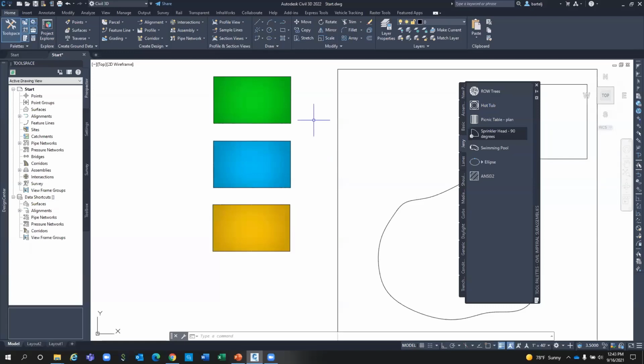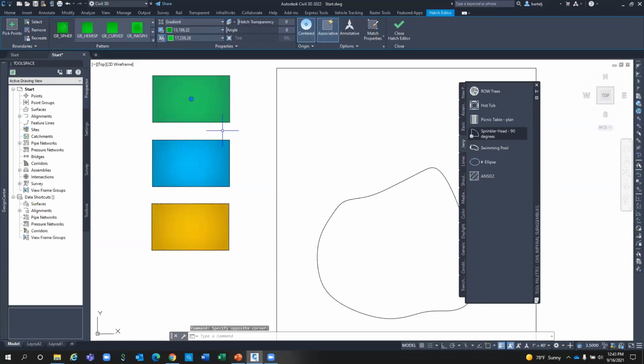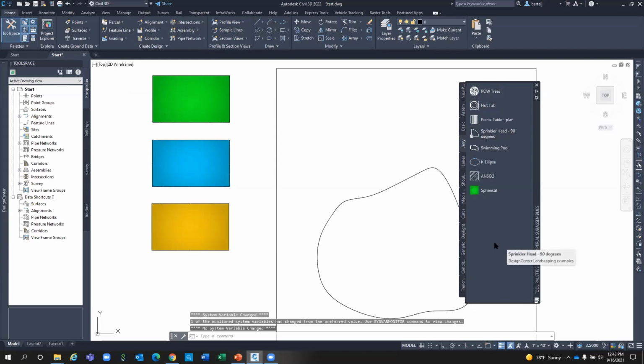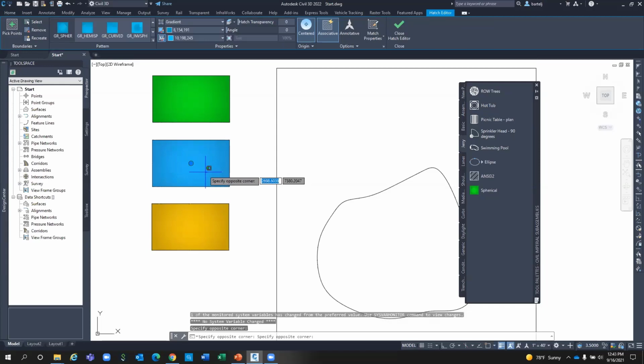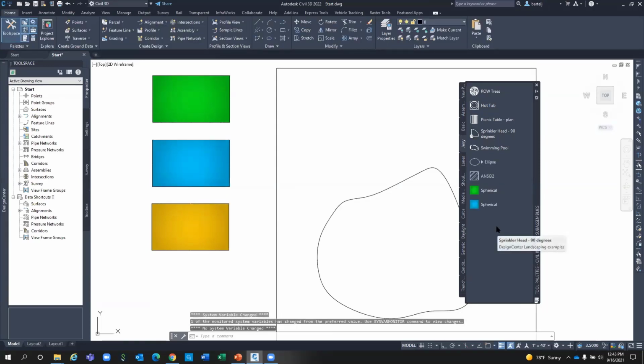I want to bring this up because I used to do this kind of like a paint by numbers type deal. But if you create gradient hatches and you're going to drag one of those onto the tool palette, the interesting thing is rather than pick and then left pick and hold, we have to pick again, and then left pick and hold, and then drag it on there. All right, why do we have to do that? That's a great question. I wish I had a great answer for you, but I don't. Just know that if I'm going to do things with gradient hatch, we have to do 3 picks.